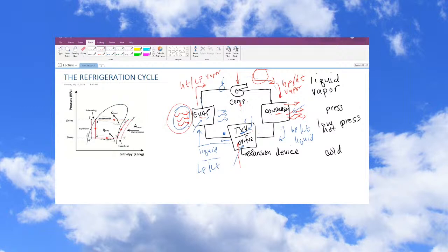And this is the means by which you do it, but it's got to be able to be removed from the car. So if you stick your front mount intercooler in front of your condenser, you're going to impact the ability of your AC system to work because you've got the airflow being restricted across the condenser, and you're not going to get as much heat out, so your AC is not going to work quite as good. Most people don't really ever notice much of a difference on that, but in really, really hot climates, it can become an issue for sure.